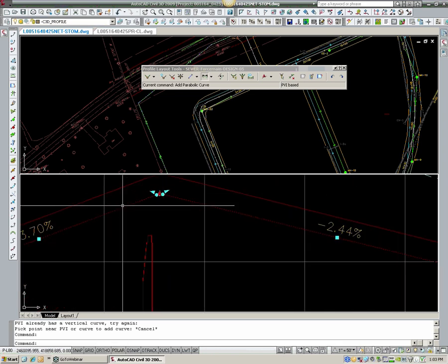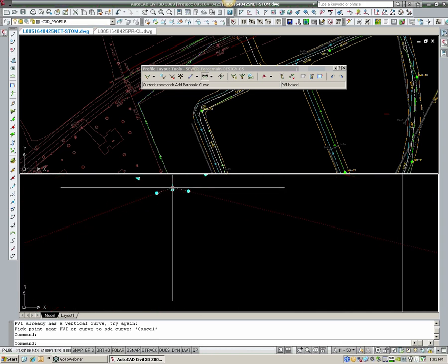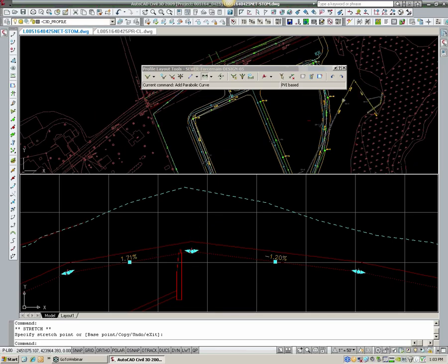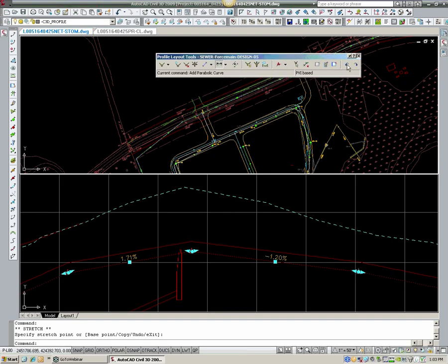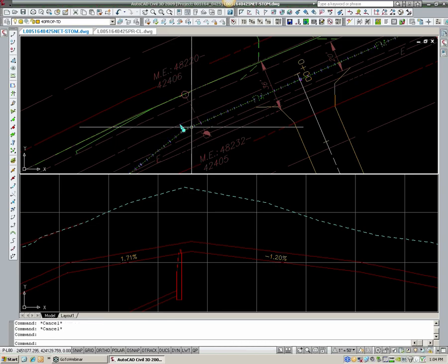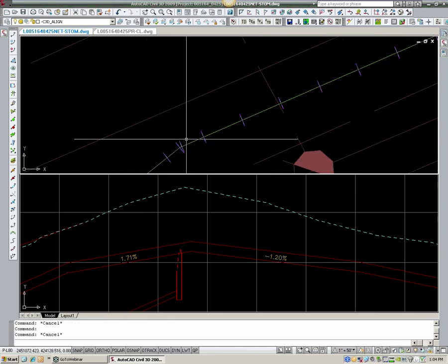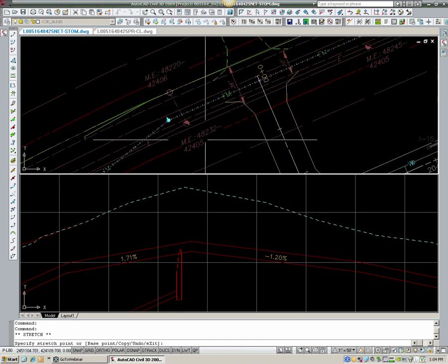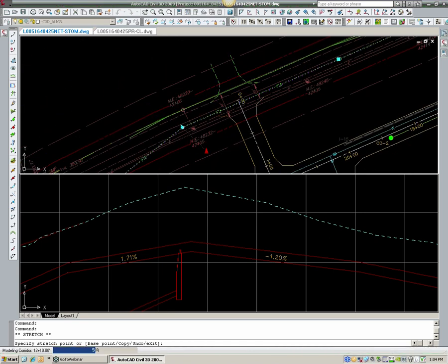But the point is, you can add longer vertical curves to this, and I can now drag this control line up and down, and it will change my force main design for me. So you got to think further ahead of, okay, if I have this force main now, then project it onto a series of other profiles, other center lines, so on and so forth. It's updating everything now. Same thing here, if I grab this alignment and move the alignment. So say I'm going to slide this alignment over to here. It's going to update my profile and my corridor model and my force main.